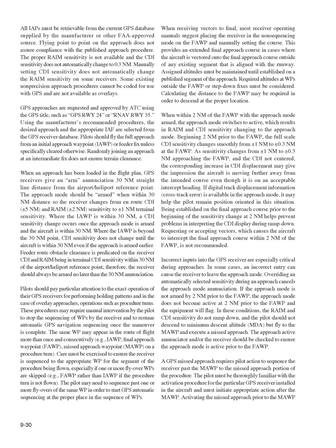Pilots should pay particular attention to the exact operation of their GPS receivers for performing holding patterns and, in the case of overlay approaches, operations such as procedure turns. These procedures may require manual intervention by the pilot to stop the sequencing of WPs by the receiver and to resume automatic GPS navigation sequencing once the maneuver is complete.